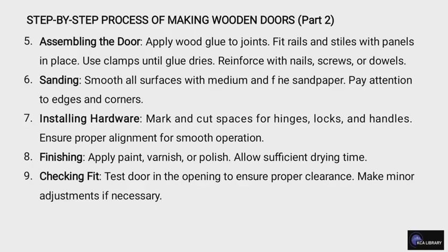The next one is finishing, where you apply paint, varnish, or polish. And the last step is to check the fit. That is, you test the door in the opening to ensure proper clearance. Make minor adjustments if necessary.